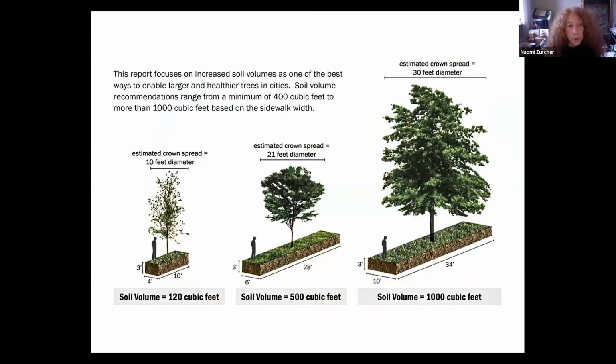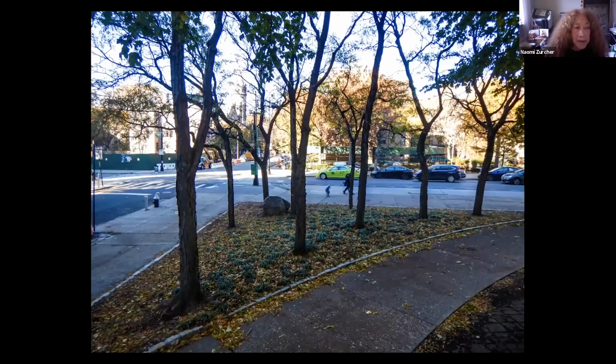Unfortunately, the present approach to streetscape rarely considers the requirements of a tree. Rather, planners and designers usually focus on pedestrians. But if a design is to be successful from an ecological perspective, the design must consider both. An adequate accessible volume of unsealed living soil is exemplified by cluster planting, affording trees' roots a communal environment, sharing a larger unsealed volume of living soil, while requiring less total space in the landscape than linear curbside plantings.